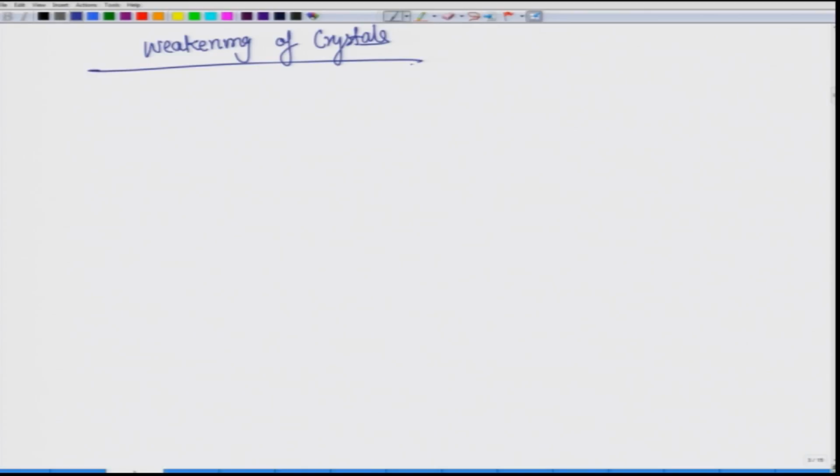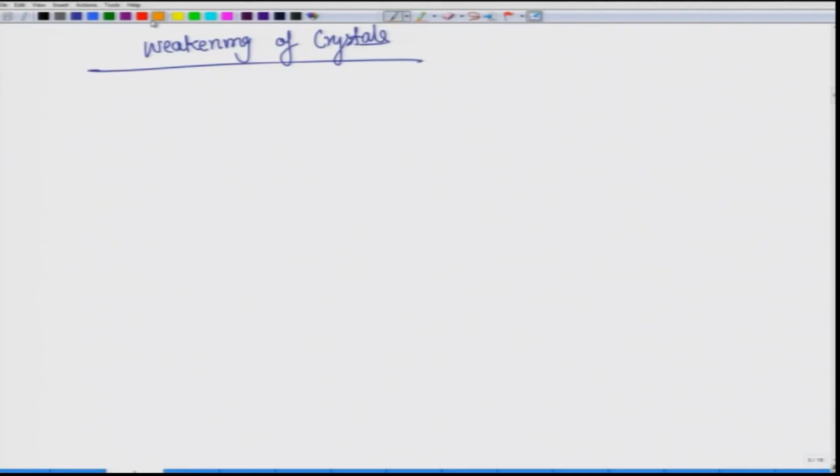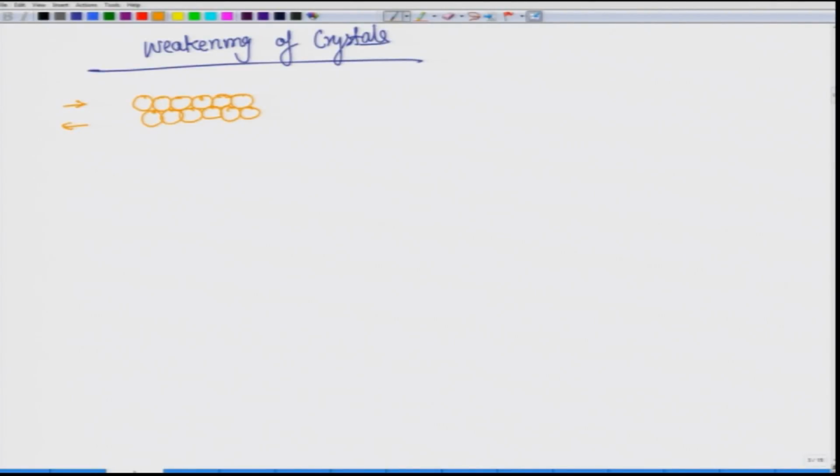Assume that you are in the era of the 1930s where people have not observed dislocation, but what you know is that materials deform at a certain strength. So, you know the yield point of the material. Now, you would think how is this phenomenon occurring atomistically. One of the models that people said should lead to deformation is, let us say you have crystals like this. Now, if you are applying some shearing or some kind of stress onto this, then for the deformation to occur, atoms must move relative to each other, and that relative motion would mean that one plane should move with respect to the other plane.